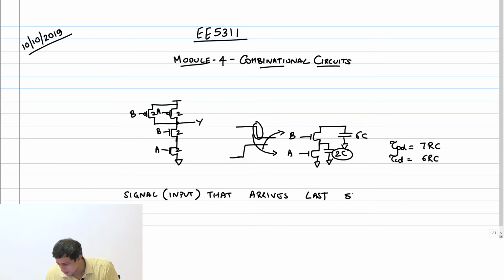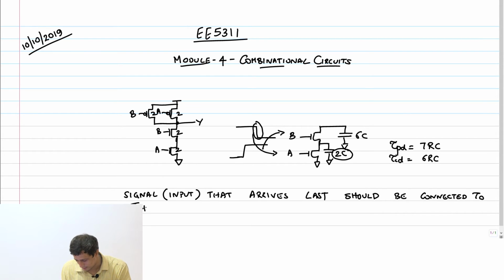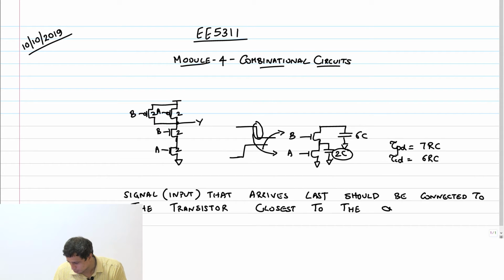The input that arrives last should be connected to the transistor closest to the output,